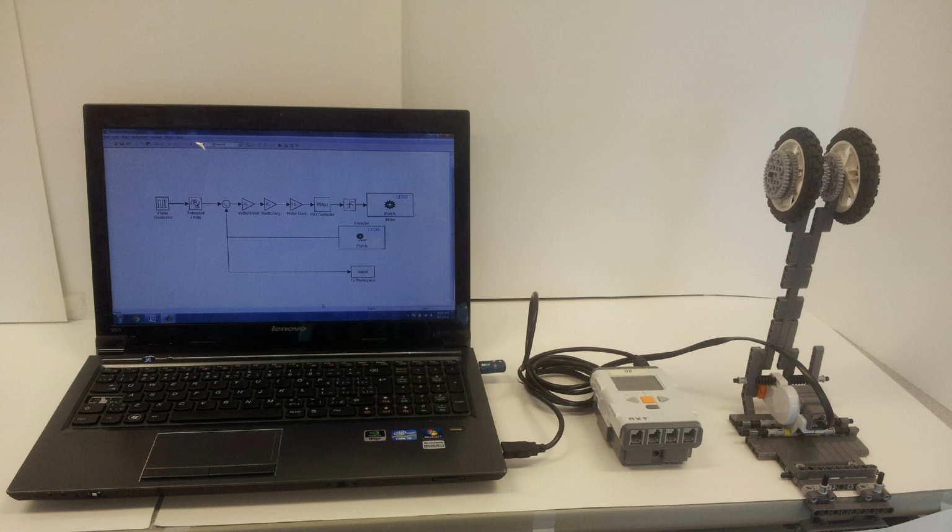Here's the setup of the inverted pendulum. On the right is the LEGO Mindstorm pendulum. A clamp is used at the bottom to prevent too much shaking. At the base of the pendulum is the motor, which pivots and controls the pendulum arm, as well as records the angle of the arm from a motor encoder. The arm is used for the rotation of the pendulum. At the top of the pendulum is the load, which acts as a weight to increase the torque of the pendulum. The motor is connected to the NXT brick via the NXT cable in port A.